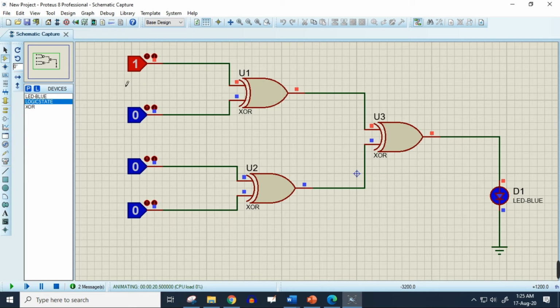Now if I change just one input here, you can see among the four different inputs, 3 of them are 0 and the other is 1. So the number of ones in our input is now 1, and 1 is an odd number. So to make it even, the output will produce the bit 1.